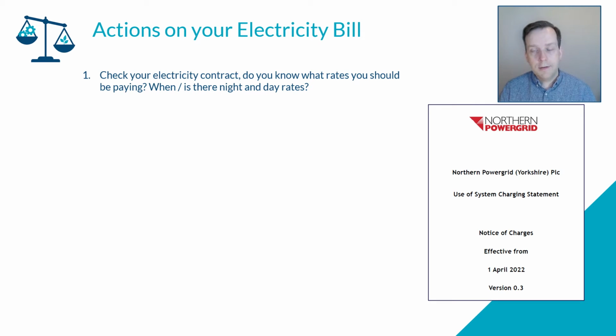So rather than charge businesses for their kilowatt hours at a particular time of day, the shift is to charge them a flat rate for the total capacity they are taking from the grid. And this is why apparent power is becoming so important and being able to manage it.